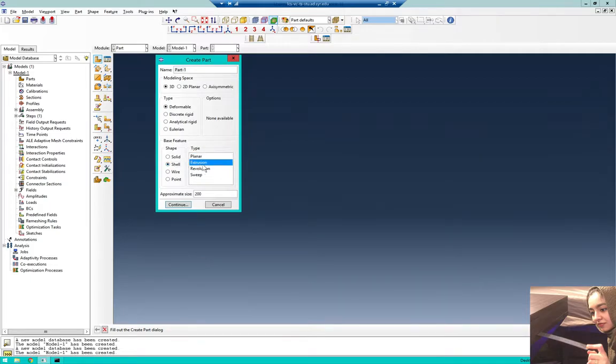And the thing is, the shell element is not planar. We're going to extrude it. So I'm going to draw just this part, just a small line like this, and I'm going to extrude it. How much? 150 millimeters. So I'm going to use extrusion here.